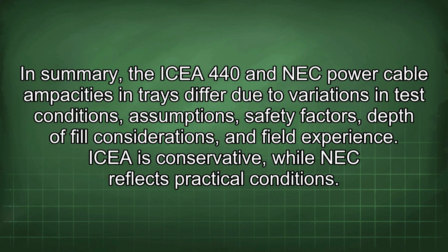In summary, the ICEA 440 and NEC power cable ampacities in trays differ due to variations in test conditions, assumptions, safety factors, depth of fill considerations, and field experience. ICEA is conservative, while NEC reflects practical conditions.